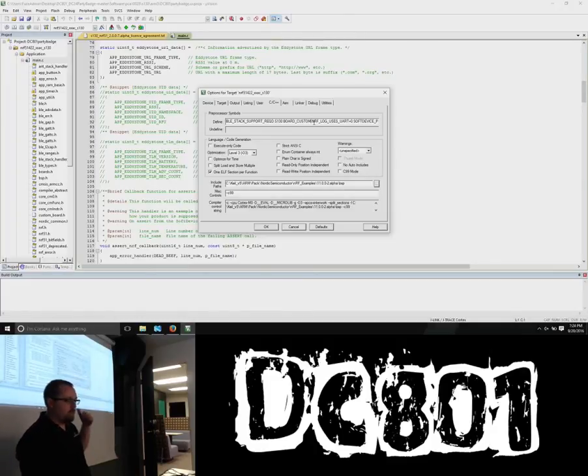And then that H file goes at this location that you have to make sure you add to the include path right here. And that gets it so it can notice what type of board you have, how you have your board configured. So that determines your GPIOs. So it determines what chipset you're using.